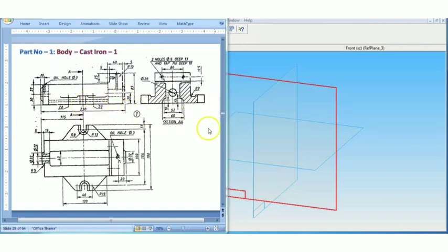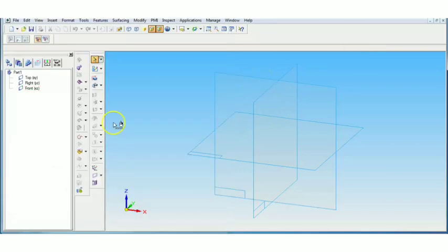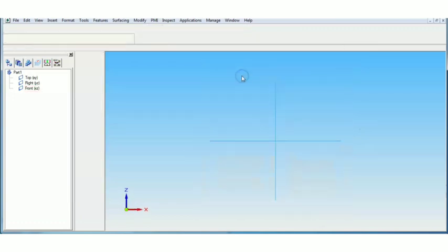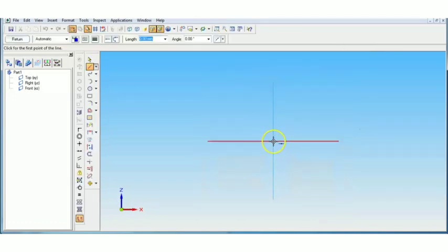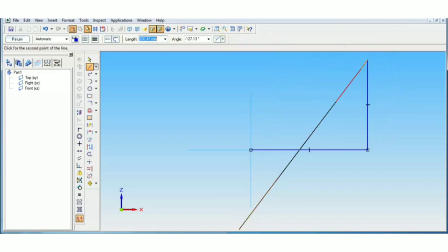So I'll start with the front plane. I'll go to Solid Edge, select the protrusion command, select the front plane. I'll start with this point. On this side, 110 and enter, angle is 0, the height is 85 mm, enter, angle is 90.